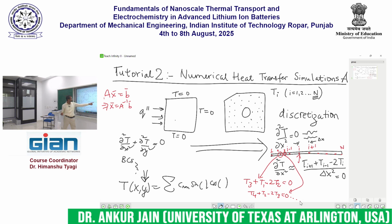I have only gone to the internal nodes. When I go to the external nodes, these two will contribute an equation based on the boundary conditions. Suppose I provide a very simple boundary condition that the temperature here is 0 and the temperature there is 10 Kelvin, say. Then the simple equations that these two nodes will provide are T1 equals 0 and Tn equals 10. Right?